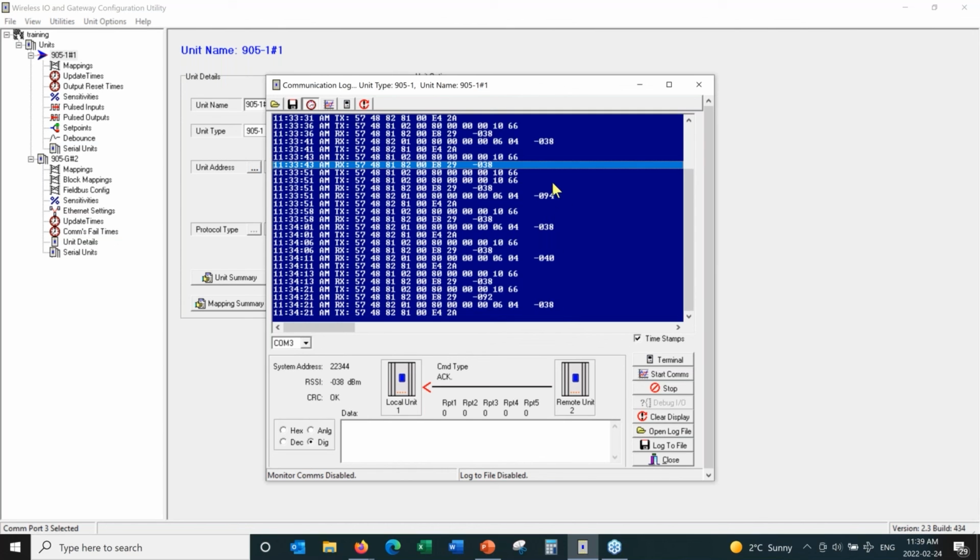Now, if these radio waves were exactly 180 degrees out of phase of one another, we would see no reception at all. But they are not quite 100% out of phase, and that's why we're seeing this very weak signal. So what do we do? We just ignore that value. This is what the RSSI actually is: roughly -38, roughly -40. This type of condition is perfectly normal. So keep in mind that here we've seen pretty consistent communications. For each transmit, an acknowledgement comes back.